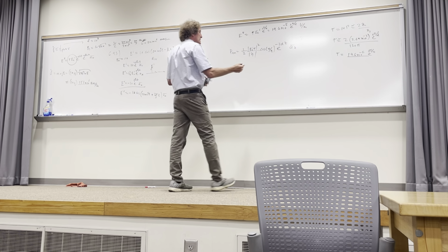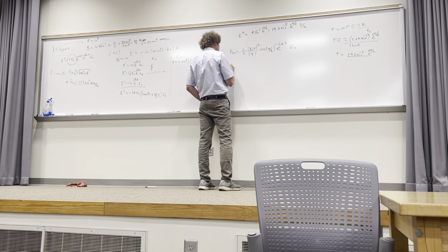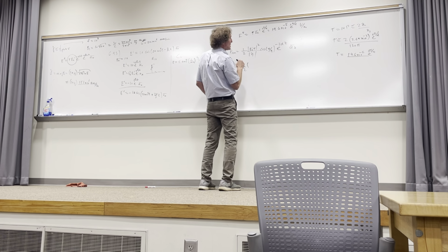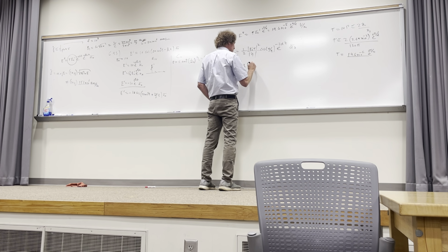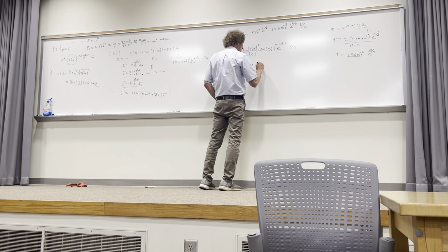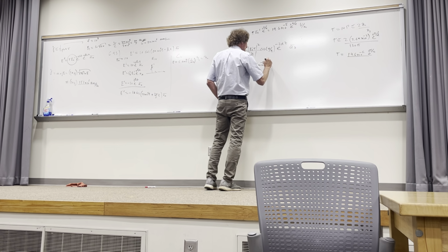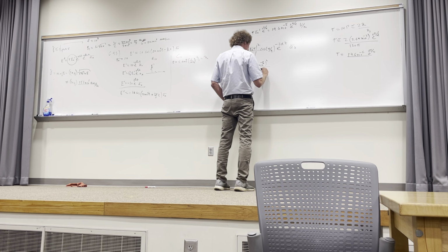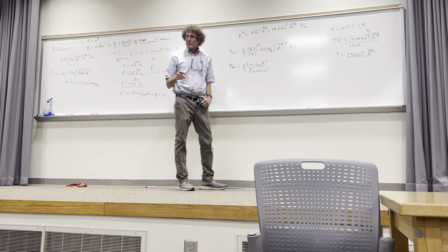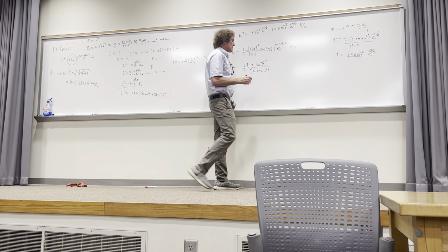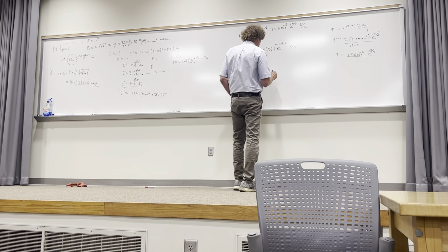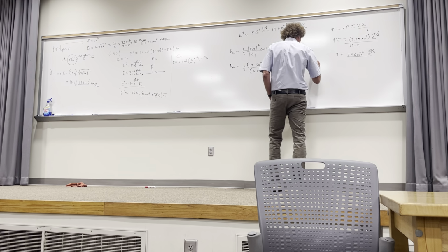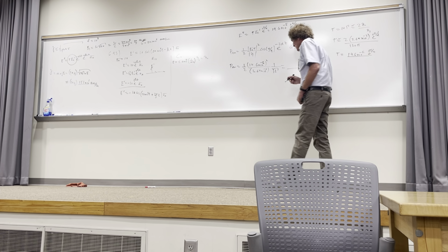At z equals 0, we can just get rid of this, and we could say the average power now, we can put the numbers in. It'd be 1/2 times 19.6 times 10 to the minus 5th squared over eta, you correct me if I'm wrong, 3.69 times 10 to the minus 3. Is that right for eta? Yeah. And then times the cosine of pi over 4. Well, that's 1 over square root of 2, so I might as well leave it as 1 over square root of 2. And that would be the average power in watts per meter squared penetrating into the steel.